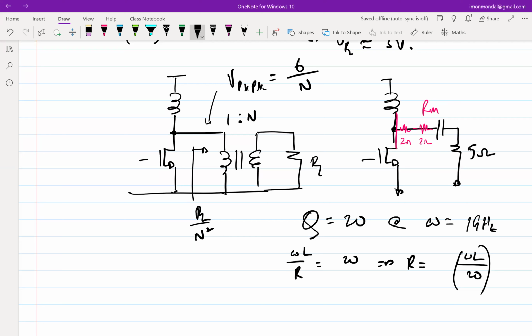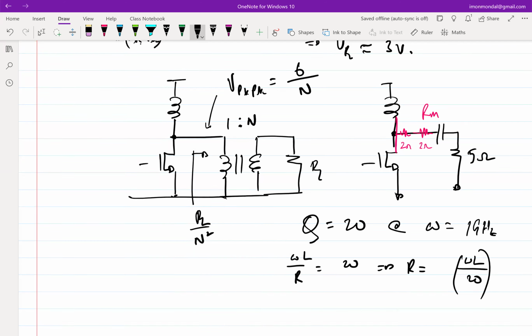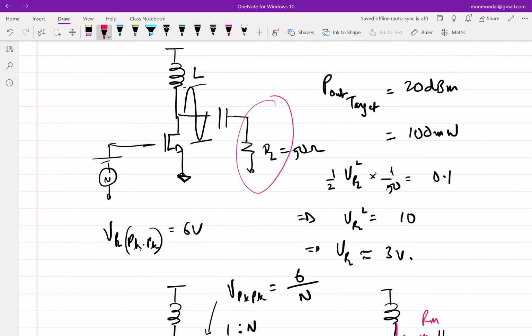That is why very high power devices, high power PAs, do not have one single matching network. They have a distributed matching network. Okay, fine. So this is as far as class A. By the way, I did not talk about the topology name. This is a class A amplifier. I should say simply amplifier, because this topology is not limited to PA.